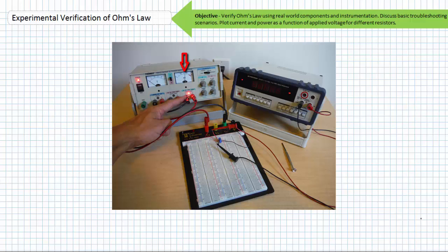Notice the power supply indicates it's in constant current mode with the LED. This is a dead giveaway something is shorted out. I know the picture shows a blank screen on the ammeter, but it's actually flashing a string of 4 zeros, which indicates for a BK Precision DMM that the ammeter is over range. Remember, some DMMs must be manually ranged. If you're reading current above that range, the DMM says so.